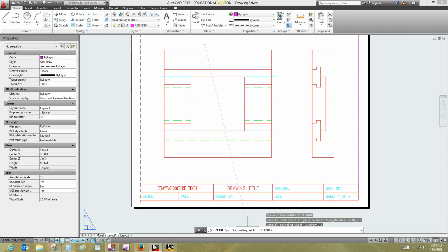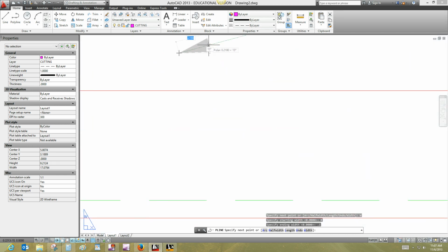My ending width, however, is going to be the widest point on my arrowhead. Okay, so I want to type in 0.1. Okay, and you can see that if I zoom in, that AutoCAD is trying to create an arrow. Okay, it's based on the parameters that I just defined. Now, according to the math that I just spoke about for how to create this arrowhead properly, the length of the arrowhead should be 0.175. Okay, so while I have my crosshairs pulling to the